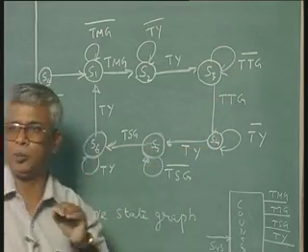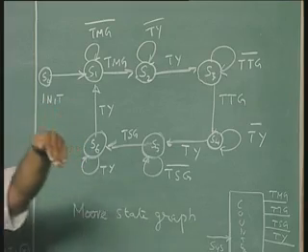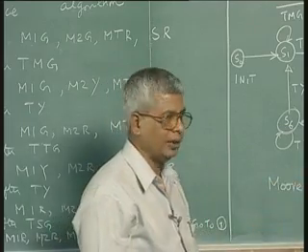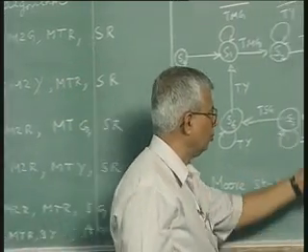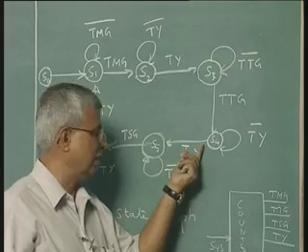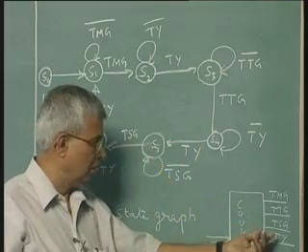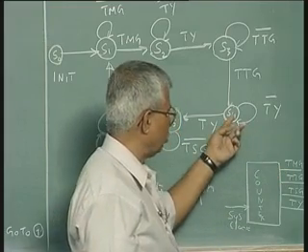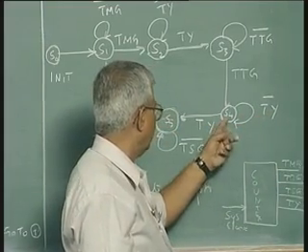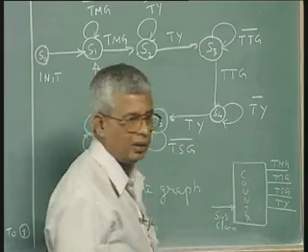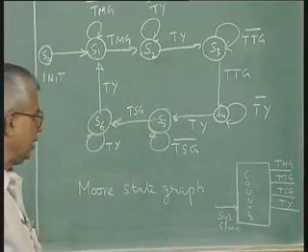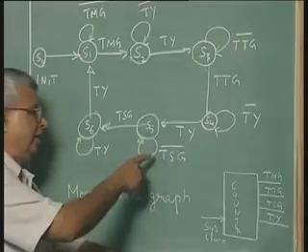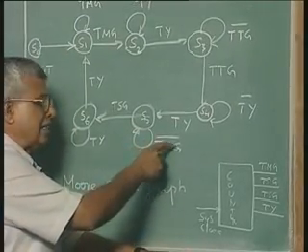S4 is again a yellow state, corresponding to that light. The turn signal light has to be yellow. That time is called the Ty. So, in S4 it remains until Ty is reached, Ty bar, and then it goes to TSG, side green. So, side green will last for a period called TSG. So, in S5 the circuit will remain as long as TSG is not reached.